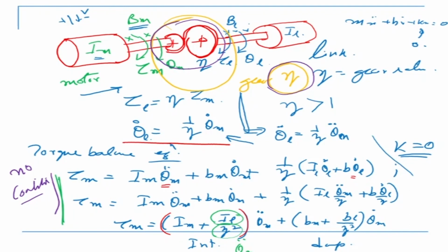Now, to include that, we will talk about how to design such controllers. When we design such controllers, we also need to look at things like stability. Okay, so we will very quickly look at this. When we say a system is stable or not stable, I had briefly talked about stability in the sense that when you have the characteristic equation, the roots of the characteristic equation should be on the left of the j omega axis. If it goes on the right, it becomes unstable. But I didn't say what stability and instability are. Okay. So let's look a little bit, very briefly.